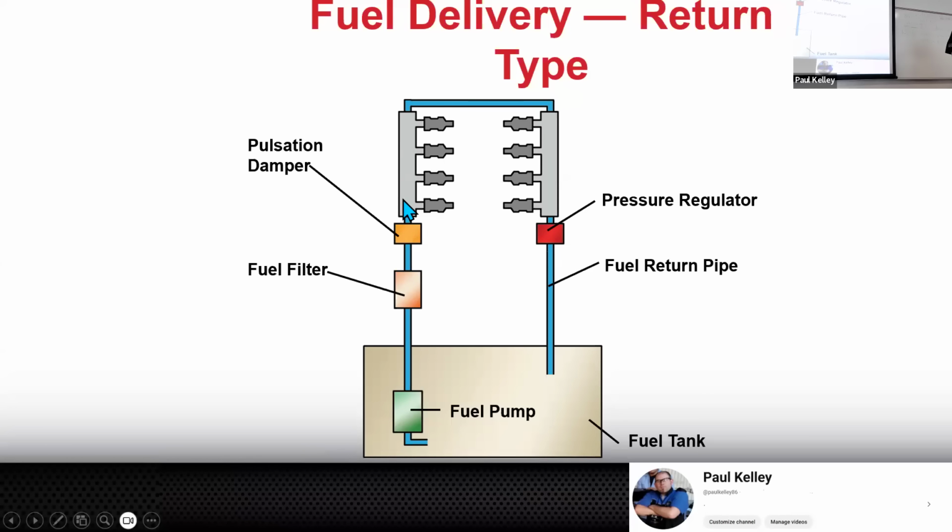There's two. And this fuel rail is going to get charged up with a specific amount of fuel pressure. And the injectors all have access to that fuel. So all the injectors get the same fuel, right? So that's why I'm saying if your fuel pump's bad, it won't cause a misfire on cylinder number one. Cylinder number one's got the same access to the fuel as cylinder 2, 3, 4, 5, 6, 7, and 8, right? So if it's a fuel pump, it's all of them, probably a crank no start. If it's a bad injector right here, that's going to affect just one cylinder, just to give you an overview.